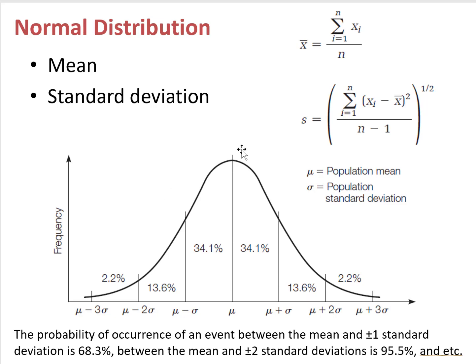So you can see if the material engineer makes the specimens which have an average strength exactly equal to the specified value, then 1/2 of the specimens will be weaker than the specified strength. And therefore, we want to make the required concrete strength higher than the specified compressive strength.